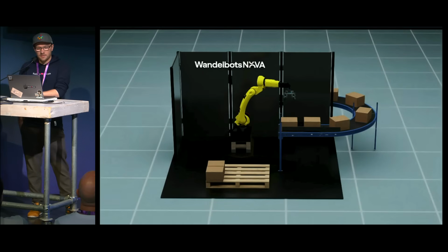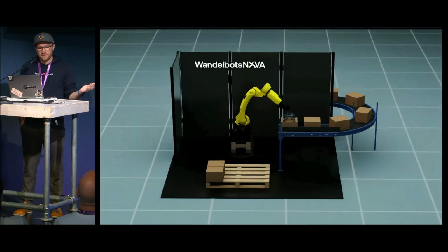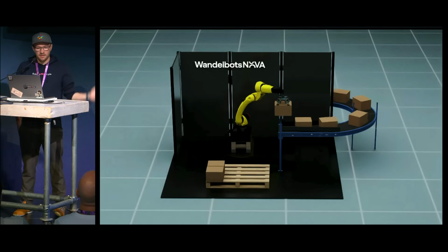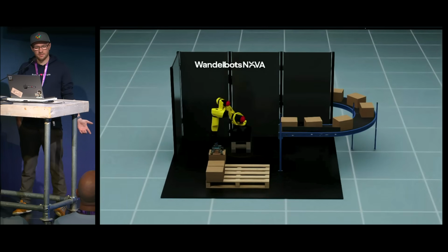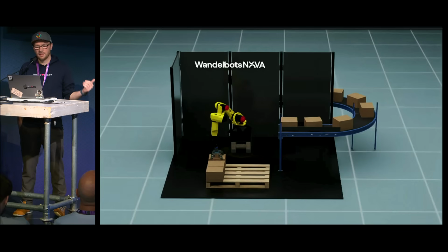And then if you have it exported to USD and in Isaac Sim, that's how it looks. We can then apply the physics, for example, the suction gripper and the conveyor belt. And then we can also integrate the entire process. For example, controller IOs were sent via the robot, and then we are using the OmniGraph nodes to control the conveyor belt, the sensors, and so on. And this allows us to put multiple cells together, working together with each other.